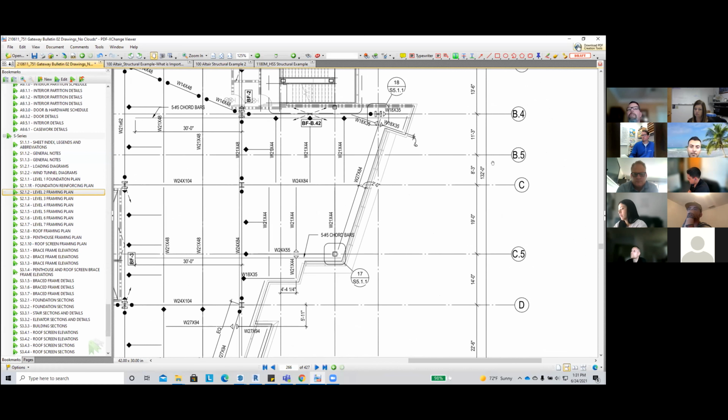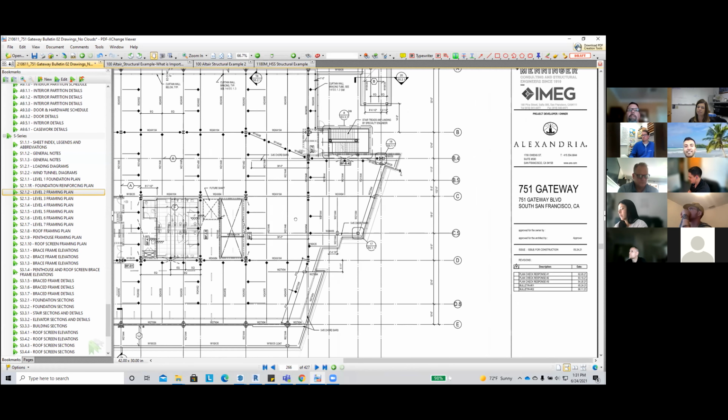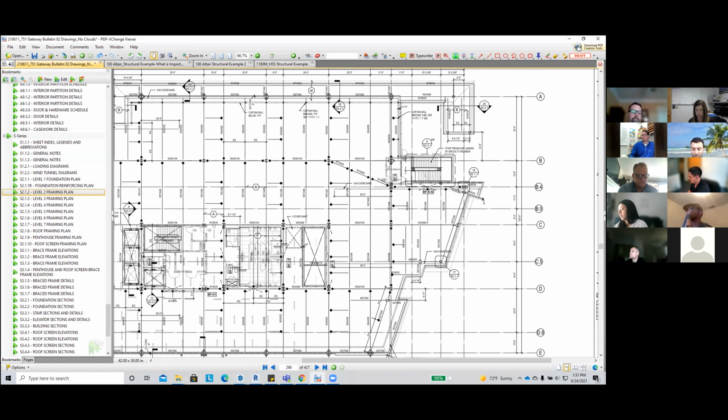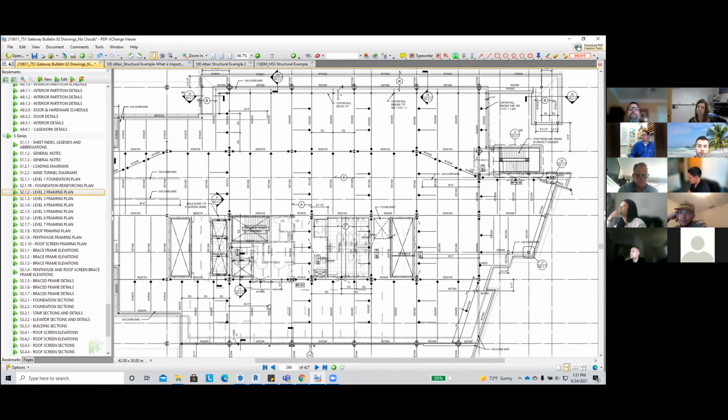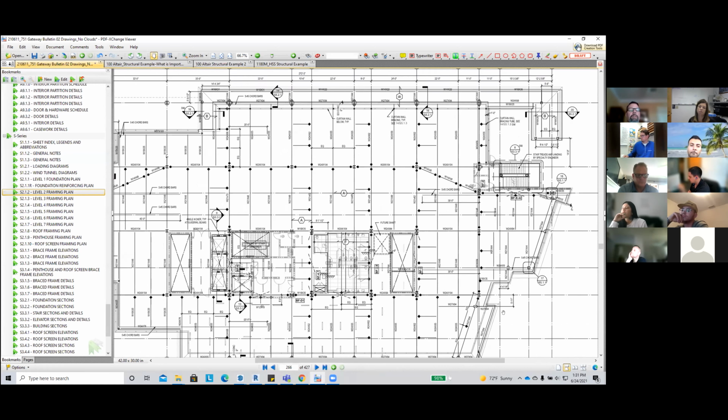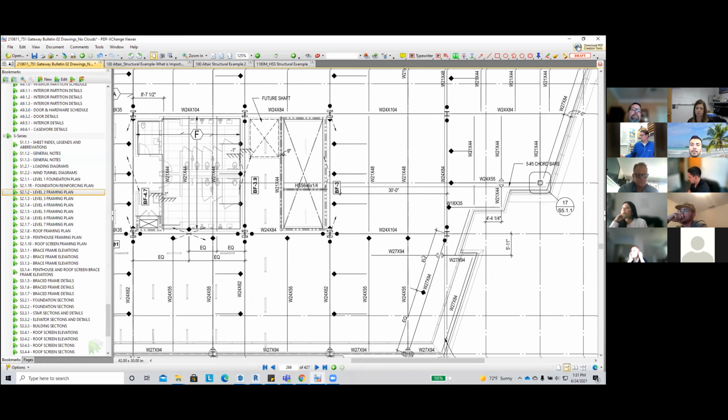Right, but then for example, the one on the left, you have the 21/44 without a dimension. There's one in the center that's not dimensioned, and as you can see, it's offset from the next quadrant up. I'd probably just scale it. I was just wondering if there was a general rule. Well, I always try to use their dimensions, and if I can't come up with it, I try to scale it, and then I send an RFI and have them confirm it. Right. Thank you.